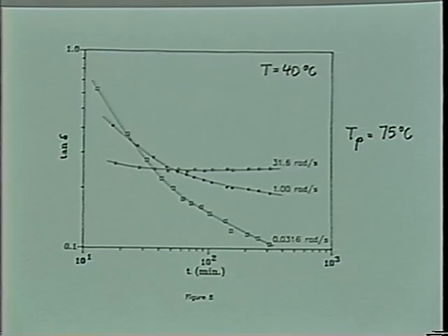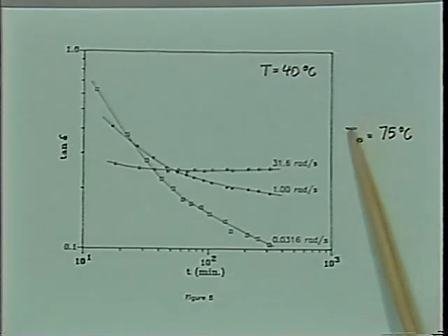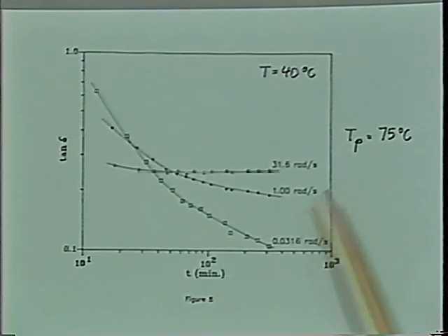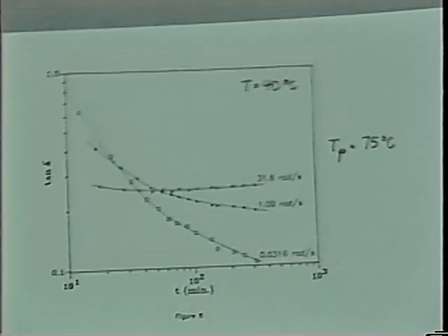crystallization causes a phase separation in that structure because the crystalline regions have purely isotactic sequences. Therefore, when you melt just barely above 65 degrees, you still will have a phase-separated region, and that type of morphology will interfere with the crystallization, and you get different behavior. I think that's interesting. It's actually very nice to take a rheological experiment and use it as an indicator of some trouble in your sample.